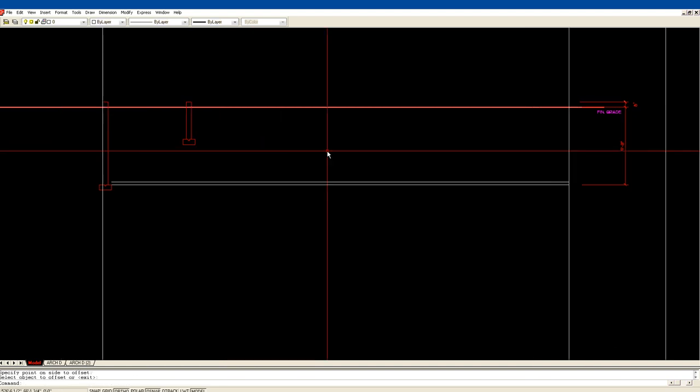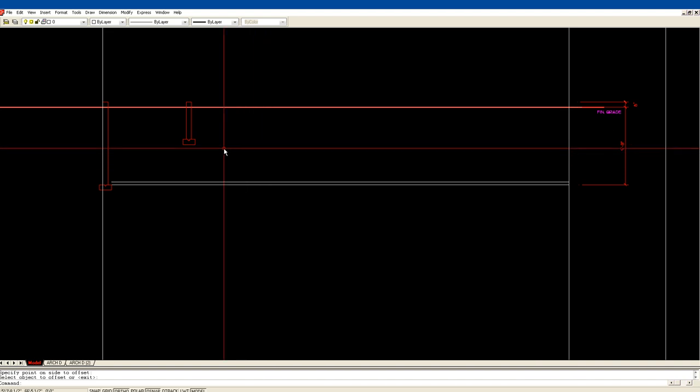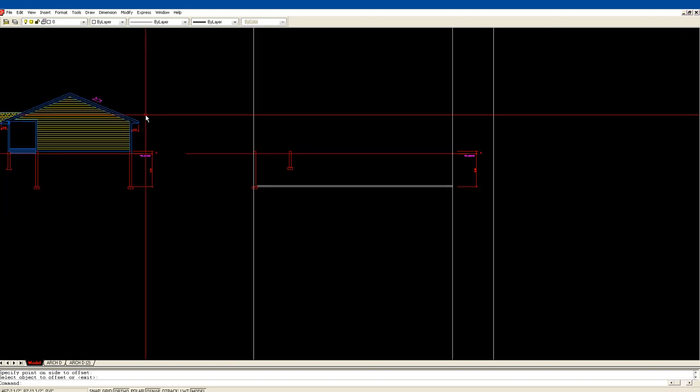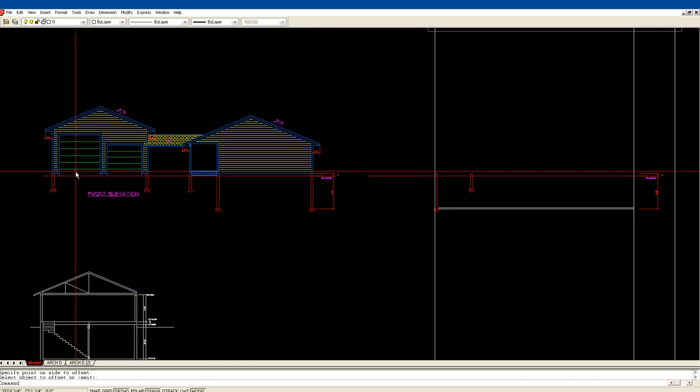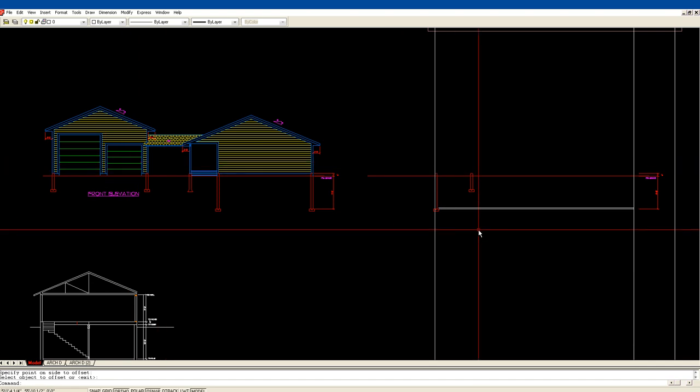By code it only has to be 3. The garage would have to be 4, they're driving cars over it. The garage slab, where he's driving vehicles and whatever, would have crisscross rebar going through it on 24-inch centers, so rebar in each direction to make rectangles.